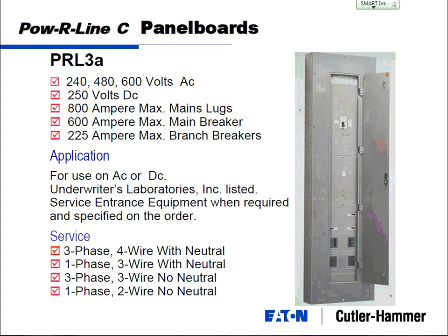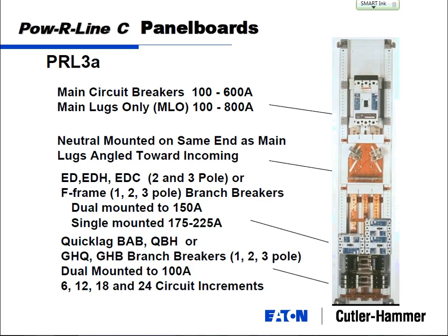And that allows you to have, you can look at this chassis a little bit. I think the next picture is a little bit better. You can have your main breaker. We actually put a neutral, we got a couple of different designs in there, but a neutral in the middle here. Down here, you've got a chassis of black breakers, just like this panel here. But I've also got some of these larger breakers right above it. So it allows you to put two types of panel boards together into one. Good hybrid panel.